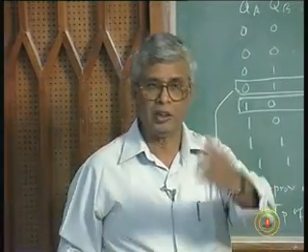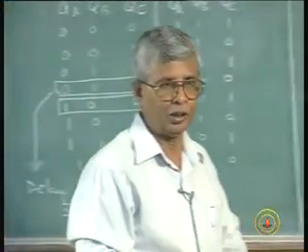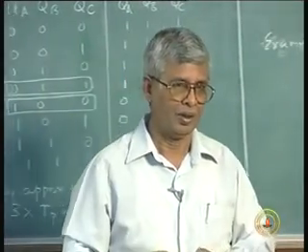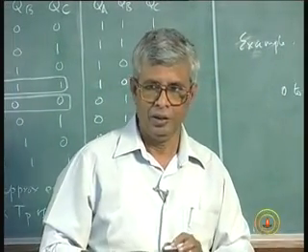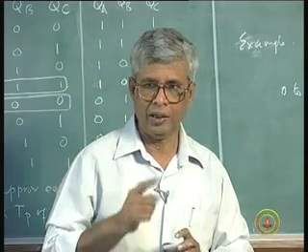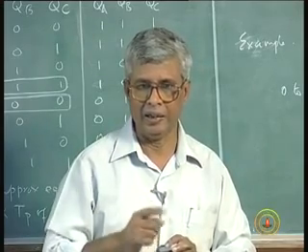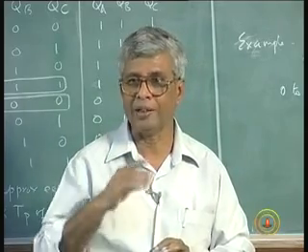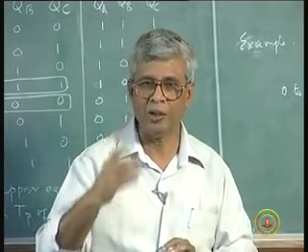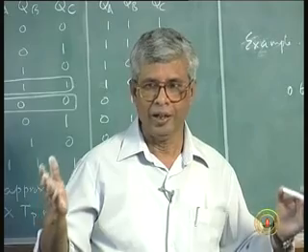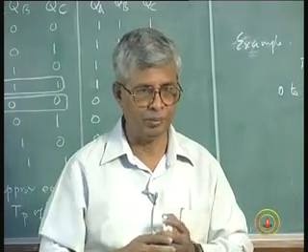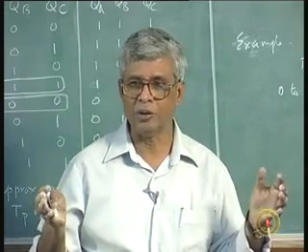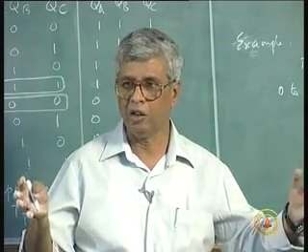Now if we are talking of these clocks, the watches, I told you just now, from 3.6 megahertz you have to count down to a second, right? 1 hertz is 1 cycle per second, and megahertz is 10 power 6, so 3.6 million to 1. You will have to find out the number of flip-flop stages required. When that is the number of flip-flop stages required, each count is going to take that much longer to materialize.